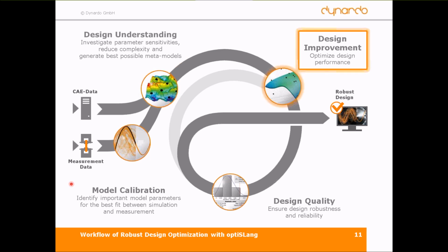You can run optimizing algorithms on the simulation, or on a meta model, and then you save on the simulation budget. Generally, if you leverage the knowledge from the sensitivity study, your optimization problem will be much, much slimmer. So always first the sensitivity study for gaining knowledge, and then a targeted, efficient optimization strategy instead of just a black box algorithm for a black box problem.